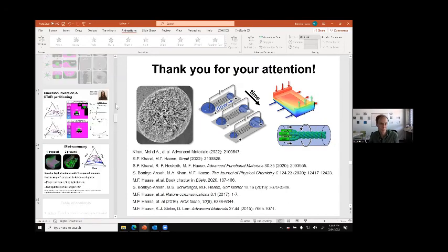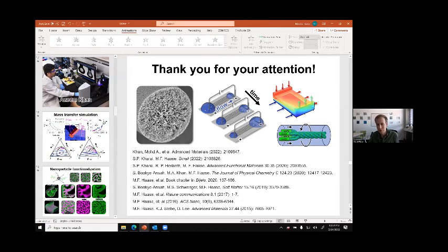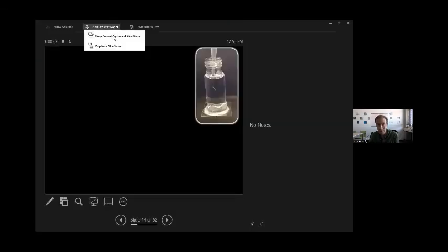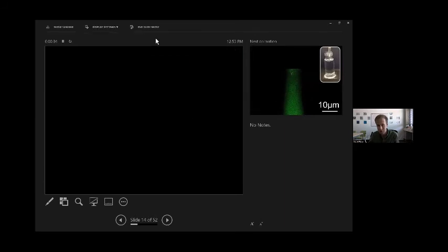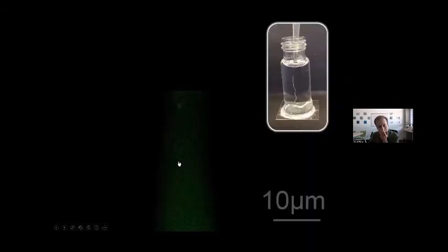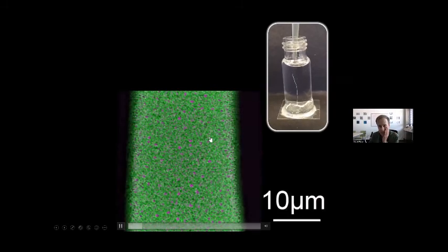We control it by varying the different parameters, such as the nanoparticle concentration and the surfactant concentration, and usually we do this on a trial and error basis, where we prepare the sample, like you see here, with a pipette, we make one of these fibers, collect it in this container, put it in the confocal microscope, check the structure, and can also quantitatively analyze the connectivity in 3 dimensions.